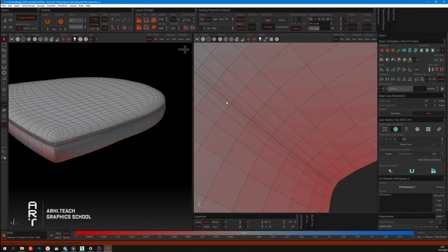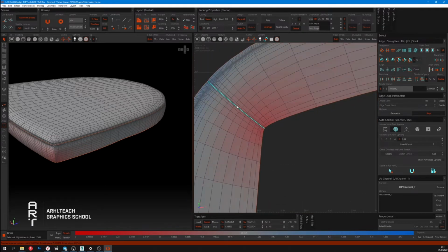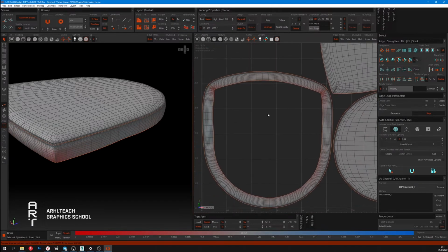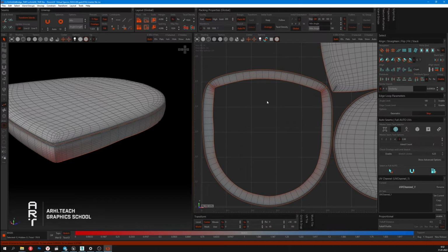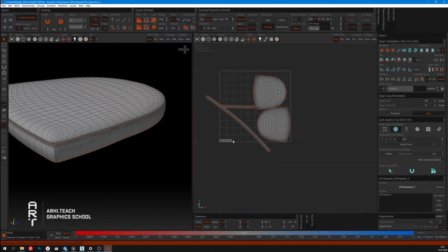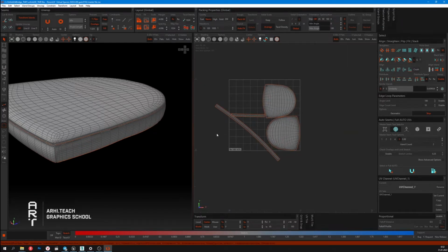Let's make some more cuts, so unwarp will be better. Then press the U Unfold button. Also, when you point the cursor on an element, the Unfold or Optimize works only for this element. If the cursor is pointed at the blank space, then the orders will work with all elements, or only with the chosen ones.